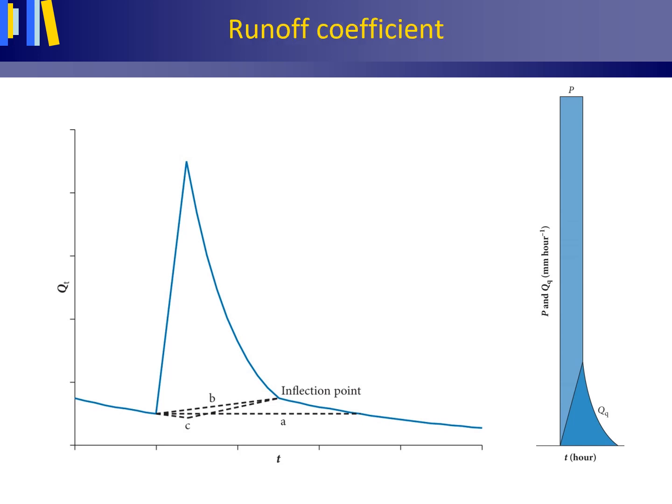The runoff coefficient of a stream can simply be determined by dividing the discharge volume in millimeter by the received precipitation volume or precipitation depth in millimeter and then multiplying by 100 to convert from fraction to percentage. The term runoff and runoff coefficient should be taken as the discharge of a stream. Another use of the term runoff is as a synonym for overland flow.